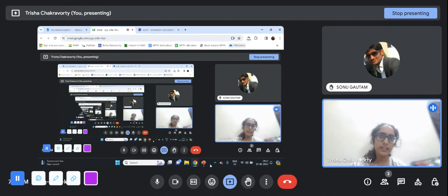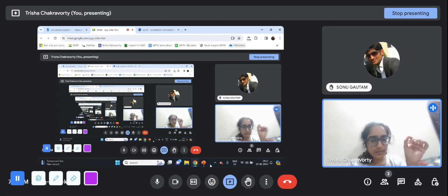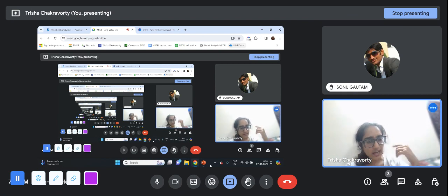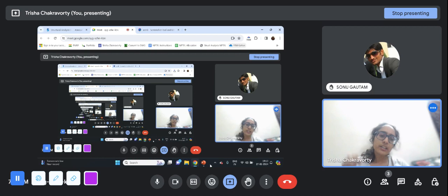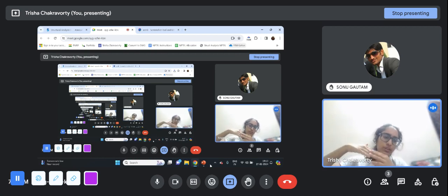Like in the moment area theorem, if I tell you to give me the slope and deflection at 3 points, any 3 points A, B, C I mark in the beam, then you have to apply your brain in deciding what pairs you will take to apply the moment area theorems. Maybe you will take A and one of the support points, and from that you will draw a tangent, because you know the support. Suppose the support is a fixed one, then we will know the slope there is 0, and you will find out at A, then maybe you will take between A and B.